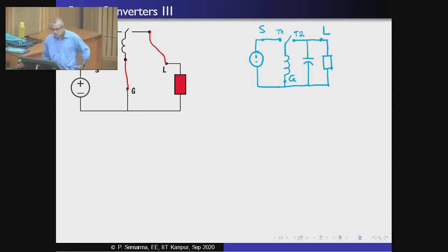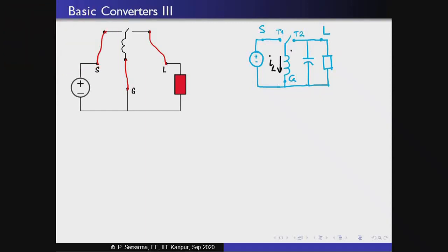And let us look at the third option then. Now, those are the reference polarities and reference directions, and those are the reference input and output voltages. Okay, so let us look at what happens to the inductor voltages. So, when it is in position T1, VL is equal to Vg, and when it is in position T2, VL is equal to V naught, pretty simple.